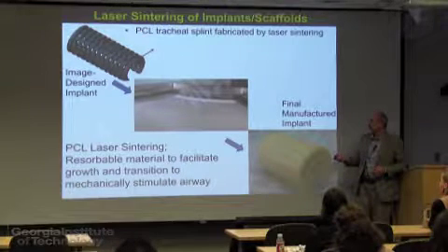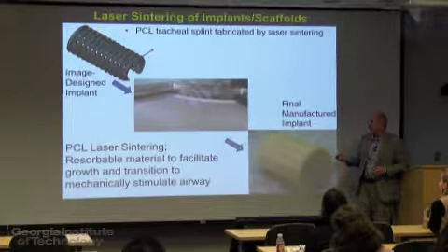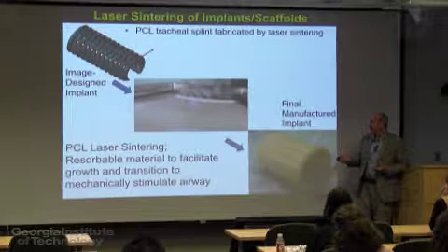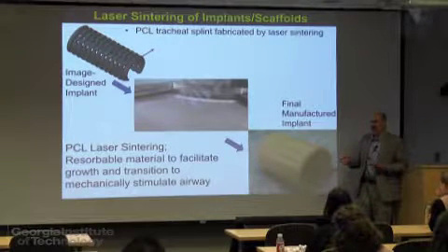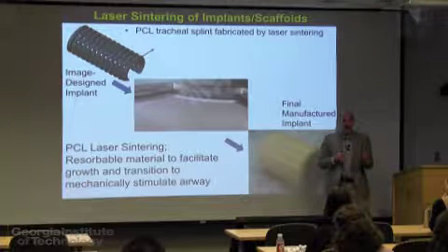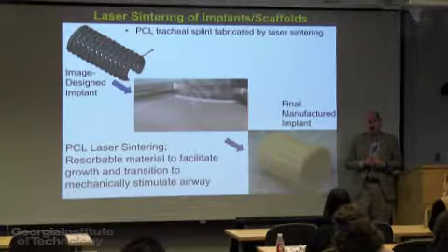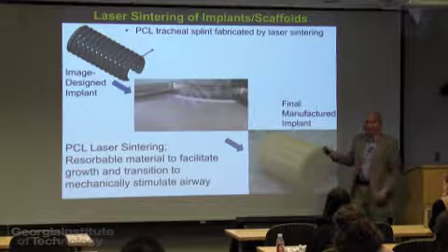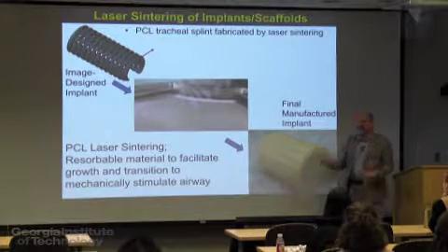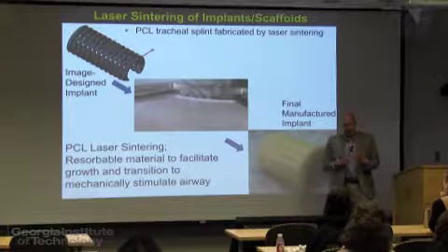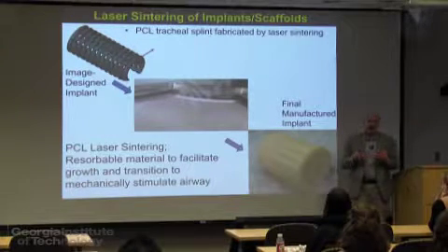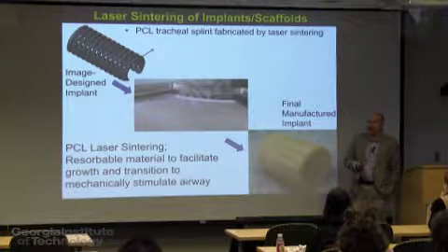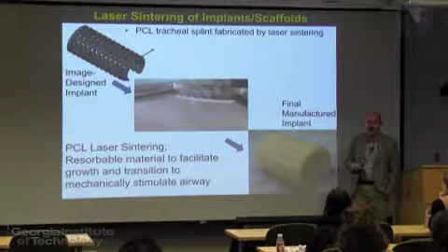With the laser-based system as shown here, which we have used in the past, the nice thing is, because you use essentially this powder bed here as support, you can build a wide variety of very complicated porous structures. The difficulty, of course, is adapting materials to use in this system. You have to be able to mill these materials and create particles on a very small scale. And they have to have the thermal characteristics that you can use within the laser sintering.